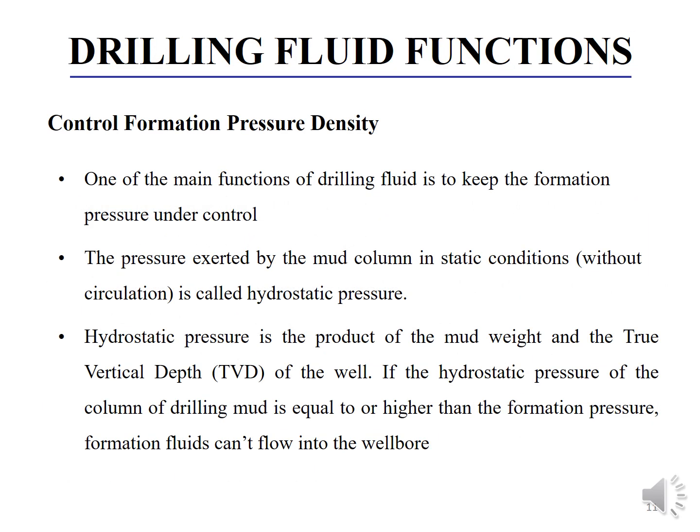Control formation pressure density. It should also be in control. One of the main functions of drilling fluid is to keep the formation pressure under control. The pressure which is exerted by the mud column in static condition is called hydrostatic pressure. So it is the product of mud weight and the true vertical depth of the well.